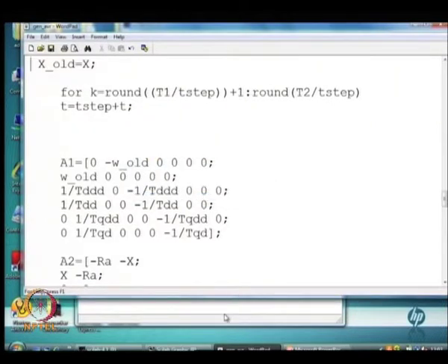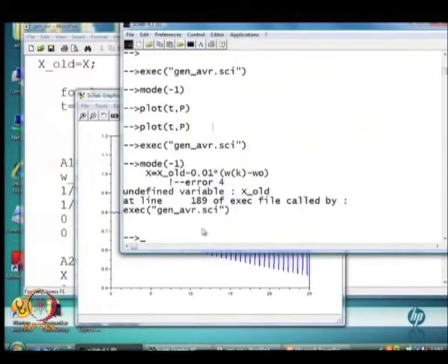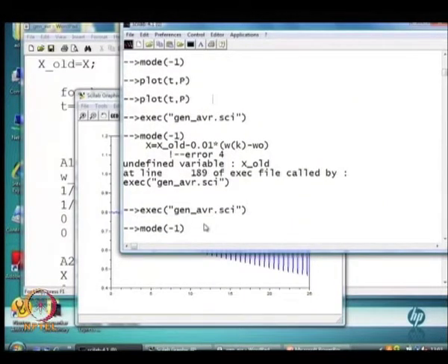I have uncommented some part which I had commented. Okay. Now, we run this again. Since we are simulating for 25 seconds with the Euler method, this takes quite a bit of time. I would encourage you not to use the Euler method, but to use the RK4 fourth order method, an explicit method, but with better accuracy. Okay. So, we just wait for a while for this to simulate.